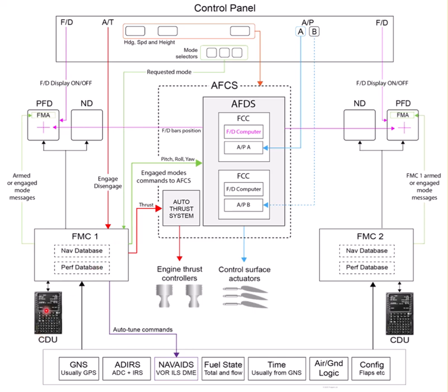So when you go to the CDU and you put in where you are, which helps to initialize the IRS, you put in where you're going to, so you've got your route started, you put in your departures and your standard arrivals, you put in the temperature that you want the aircraft to think it is if you want to do a derated or flex takeoff, you put in your winds, and this all helps the FMC to work out the best lateral and vertical route profile for you.